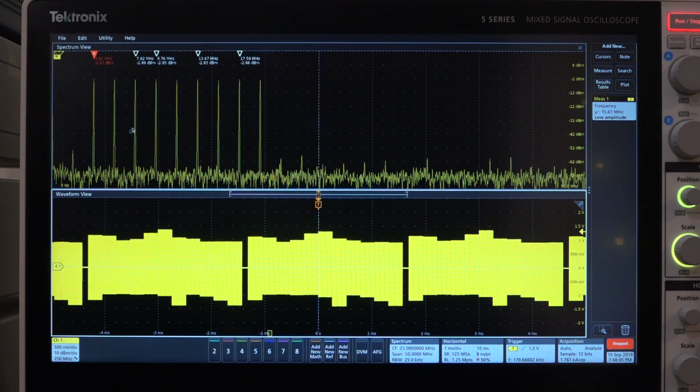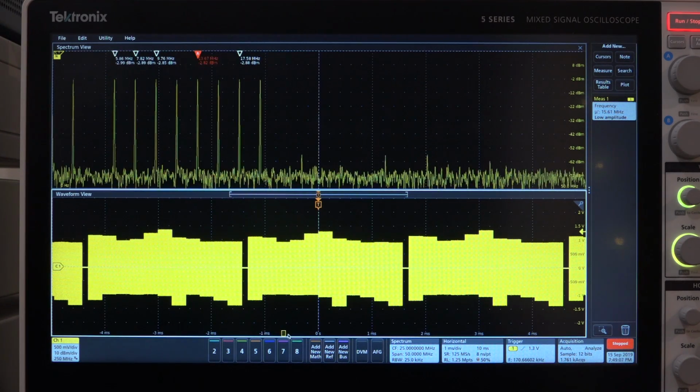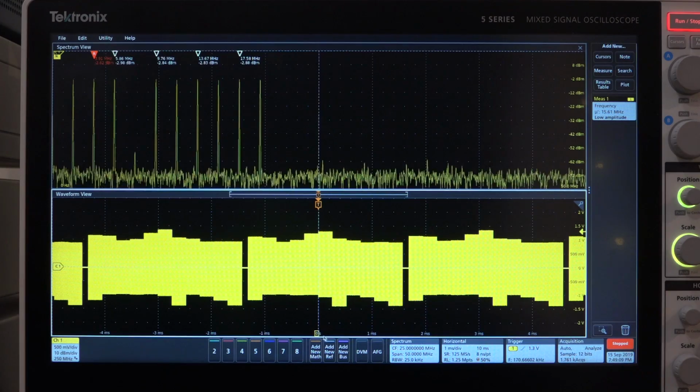This is called the missing tone test, which means that all of these tones are going to create intermodulation products, landing on top of each other and filling this missing tone all the way up. Eventually, if the signal of this circuit was really nonlinear, this would fill up all the way to the top. You can see some other effects of it, second harmonics and so on, showing up later as well. We can go ahead and go to the second section here. There you go, another missing tone, another one, and so on.